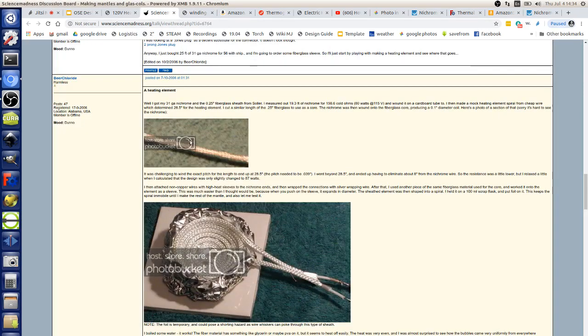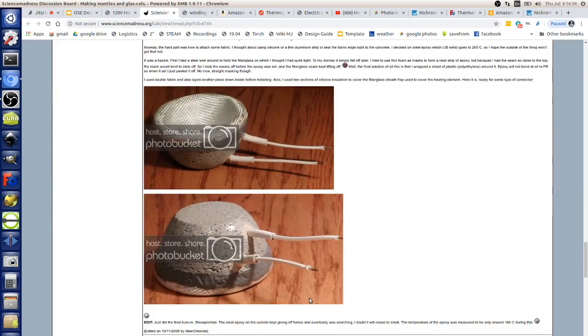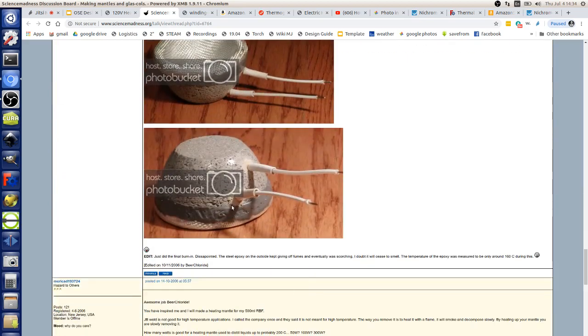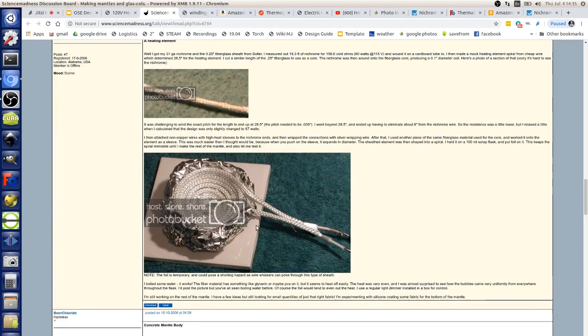We never got around to this, but I think from yesterday's experiments, we found that this is absolutely desirable. So you can have, we had 13 feet, about 4 meters length. Well, you have to put that into the second sleeve. So what you have there is the inner wire with the wire wrapped around it, and you send that through, and then you have full insulation around that. And once again, here you're crimping to whatever else you have. And here was a great application of one of these. This is nice and tidied up, but this is how you do it. Okay, so that's the technique for building these things.